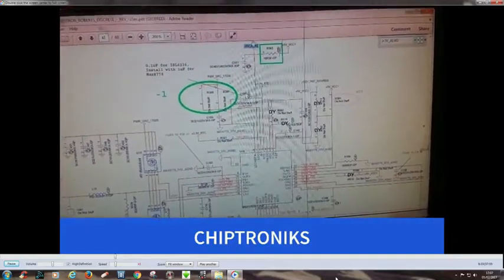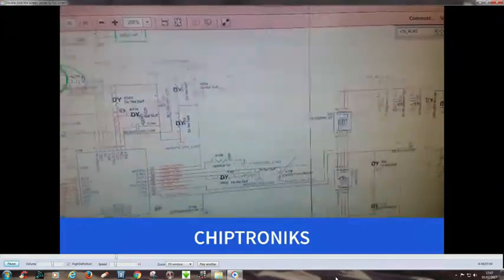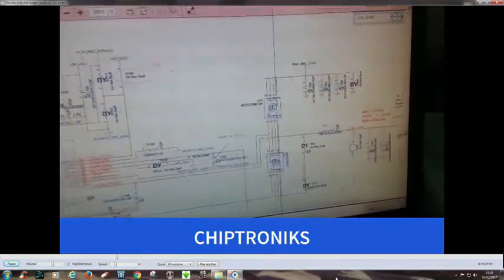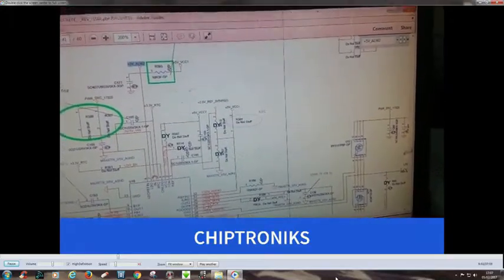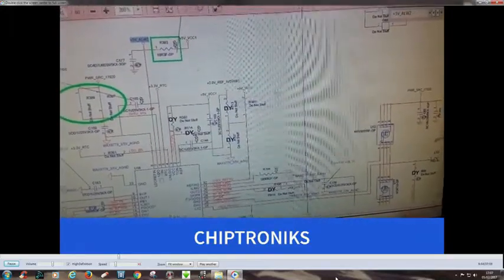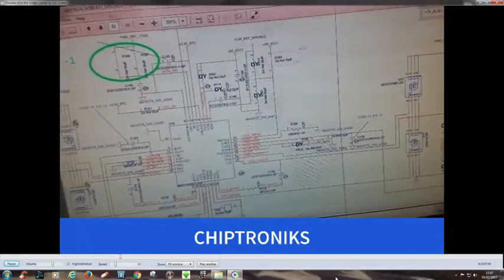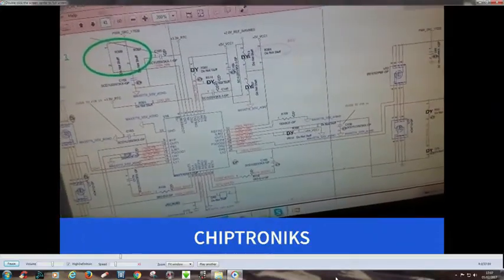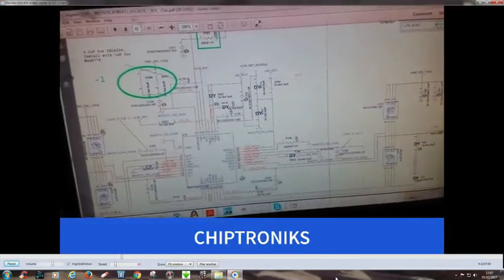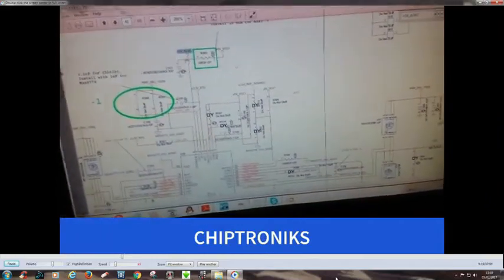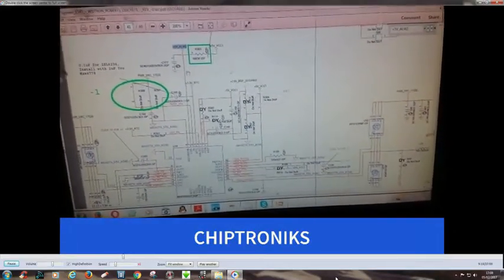You can see this 5 volt ALW2 is the LDO output of the 3 volt 5 volt regulator IC. If this LDO is not coming, then we have to check whether this IC is receiving its proper input or not. This is MAX1702, U18. So now on the board we'll find where U18 is, and we'll check for this 5V always, 5V underscore ALW2.